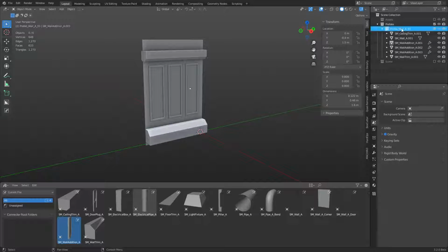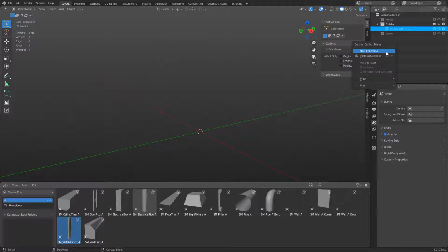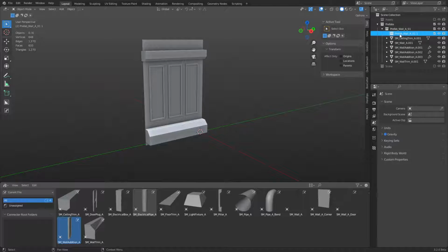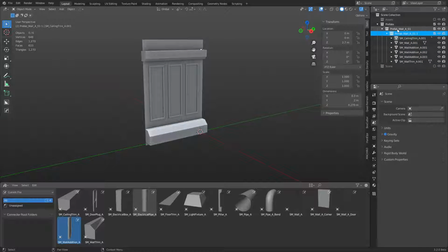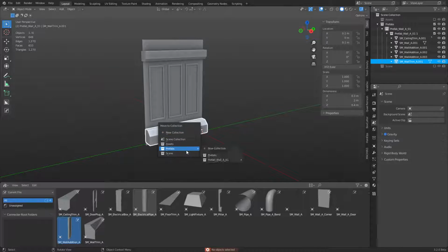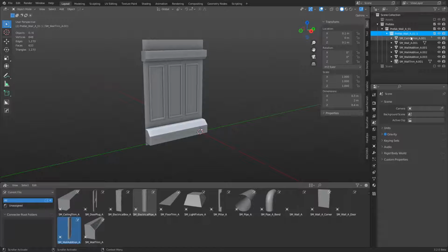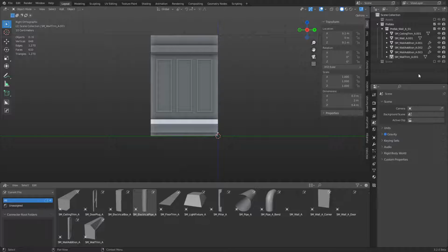That's it. So that's prefab wall A, and we can actually just uncheck that, hide it, create a new collection here. You can see it puts it into this one for some reason, which is really weird that it does that, but all this should be a part of prefab wall A. We'll press N real quick. You see prefab wall A has 2 collections. So there's an additional collection in here we don't actually need. So that can go. That's what happened. Sometimes that happens. You got to find it.